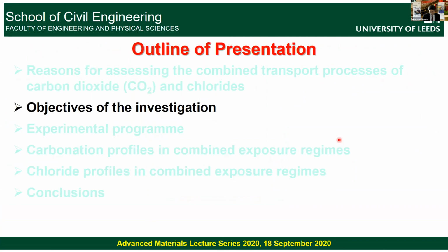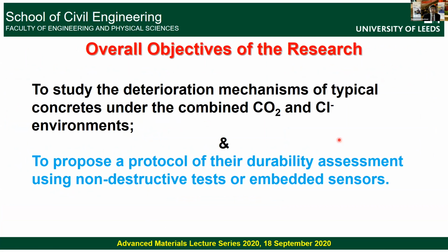So the objectives of the investigation, primarily to study the deterioration mechanisms of typical concretes under the combined CO2 and chloride environments. And also using the data to propose a protocol for the development of durability assessment using non-destructive tests or embedded sensors. There are different models available for predicting service life, and I just wanted to use the data from this particular strand of the work to highlight what are the existing limitations, what changes are needed to existing models.